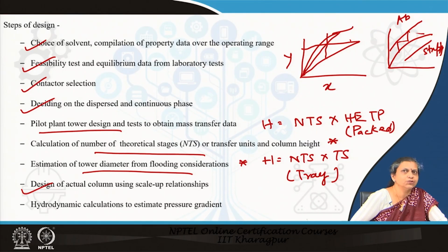In this case also we can do this under very special circumstances. Generally the process is not so straightforward, and you must have guessed the reason for it. The primary reason is the miscibility of the feed solvent and the extraction solvent between each other, as a result of which for most of the cases we have to refer to ternary plots or rectangular plots.